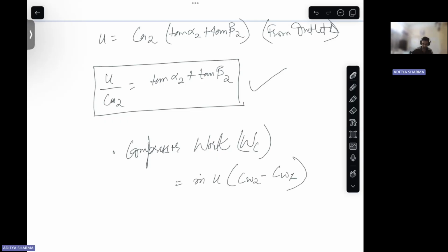The work velocity or tangential velocity and your axial velocity, these two are being considered in this axial flow compressor. Then from the velocity triangles, this can be written as U CA times tan alpha 2 minus tan alpha 1. From the velocity triangle, you can see this.